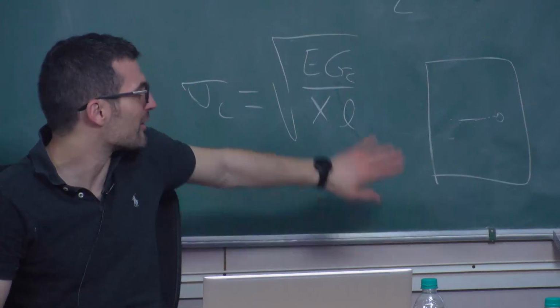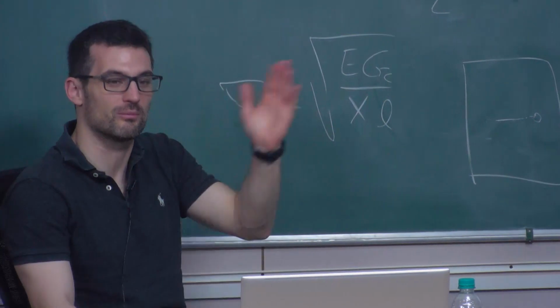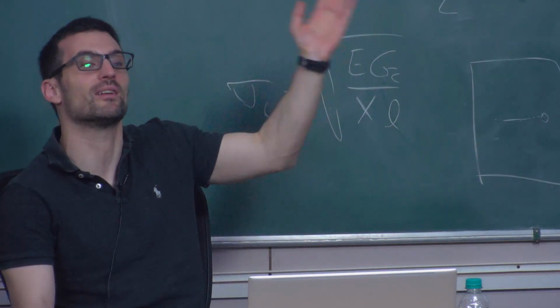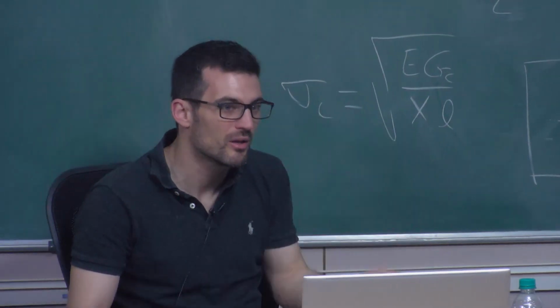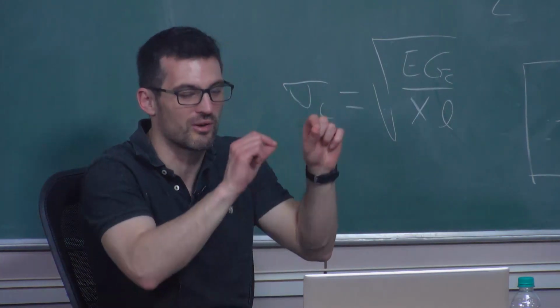So far we're assuming this will get us far. It seems to, since we can capture SN curves, which are strength dominated, and Paris law with the same scheme. So things seem to be going in the right direction, but it is an open question. I guess one could refine the details further.